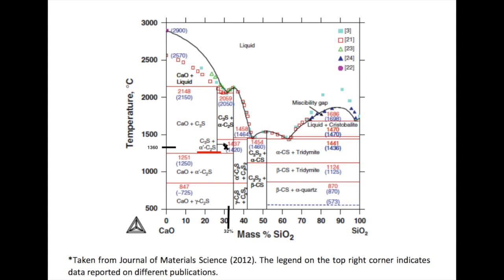So now for reaction G, if reaction G occurs at a temperature of 1633 Kelvin, and assuming the clinkering process stops at that temperature, what would the final phase for belite be? And to do this, we have to assume that there's only calcium oxide and silicon dioxide left in the system. So assuming this, we have a proportion of 1/3 of silicon dioxide and 2/3 of calcium oxide.